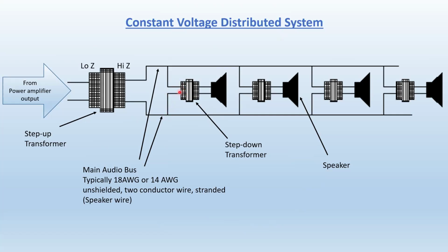And if you connect the black common to the yellow, which is going to be 1 watt, and if you have an amplifier that is capable of outputting 100 watts, and you tap each one of those at 1 watt, then you can use 100 speakers tapped at 1 watt. That's how simple it is to calculate the power, how many speakers you can put on one channel. If you tap those at 2 watts each, which means at full volume that station is going to grab 2 watts, then you can connect only 50 of those. Simple, right?